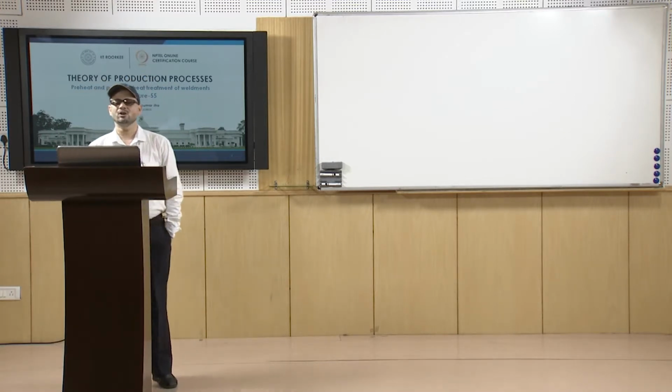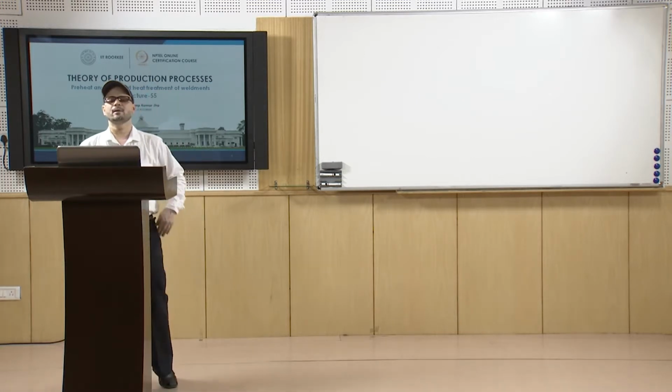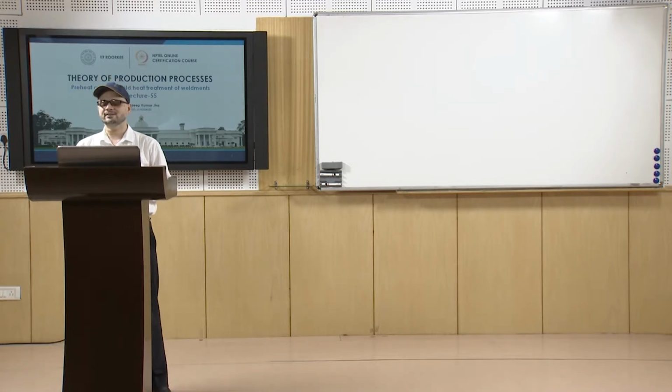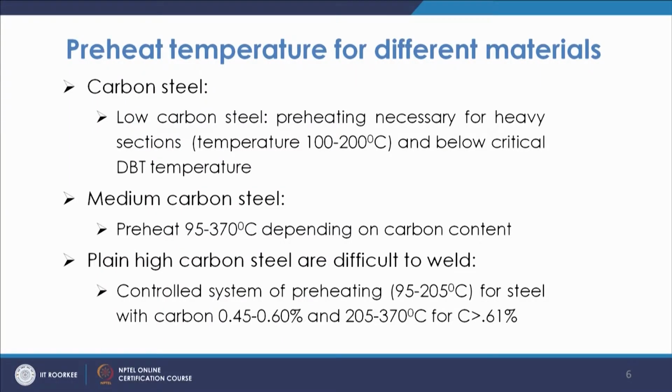Now, it is also seen that if the material does not have an impact value of about 8 to 10 joule, then there is considerable danger of cracking under the stresses. So that value of toughness is required to be there.